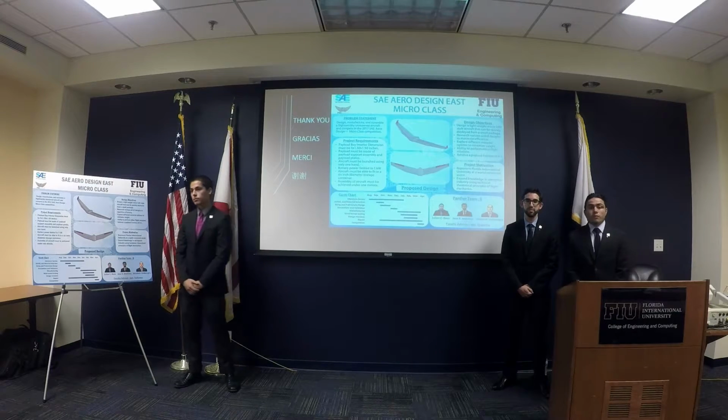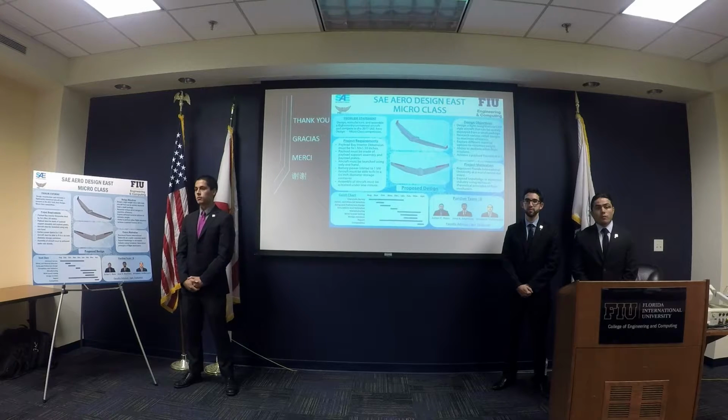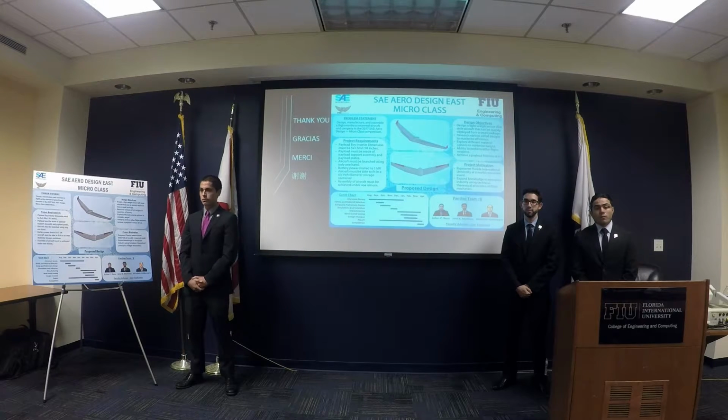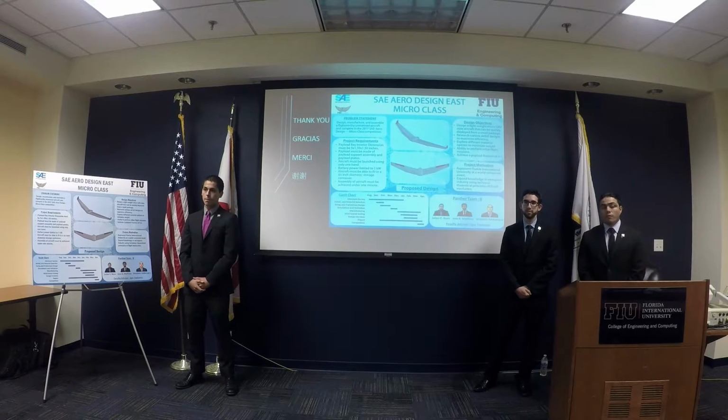Yes. Now, something I've always experienced is the lack of stability with flying wings. From the shape that you're showing here, what you're looking for to increase your stability is a 90-degree angle on both of your wing sections. You're showing a very shallow angle, which worries me that your plane is just going to go into a spin and you just won't recover, or any abnormal loading will cause it to go into a flat spin and come down to crash.